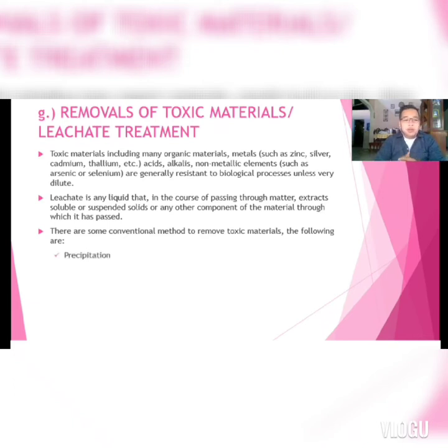First, we will tackle precipitation. Precipitation is the most common method for removing toxic heavy metals up to parts per million levels from water, since some metal salts are insoluble in water and get precipitated when the correct anion is added. Although the process is cost effective, its efficiency is affected by low pH and the presence of other salts.